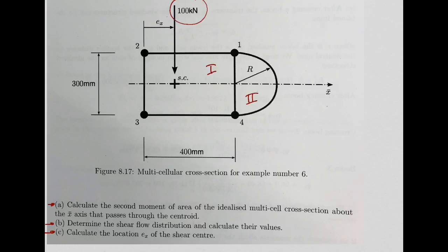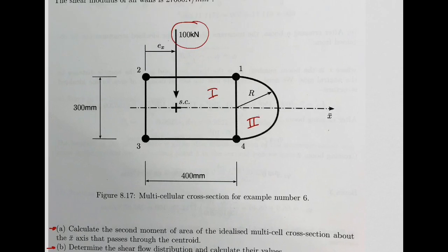Could you repeat what's the shear center? Yeah, shear center is, okay, you have the lift, right? On the wing, for example. You need to design your wing so that the lift, or the resultant of that lift, let's say, is located in the shear center. Why? Because, as I'm going to show you, if this force of 100 kilonewtons is located at the shear center, the cross-section will not rotate. The rotation or the twist angle is 0. So that's a very important point.